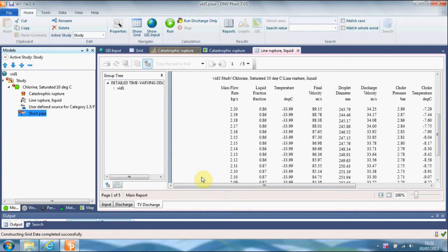If you need to change some aspect of the input data, you can edit this scenario and rerun the calculations, whereas if you use a user-defined release scenario, you would have to edit and rerun the time-varying scenario first, then create a new user-defined release scenario and delete the previous one. Before you insert the short pipe scenario, rename the time varying scenario to add "time varying not needed".